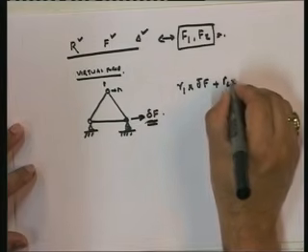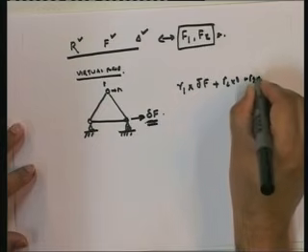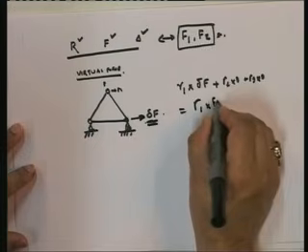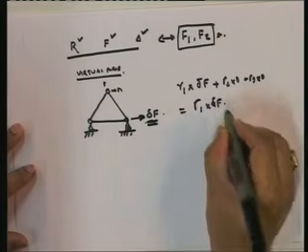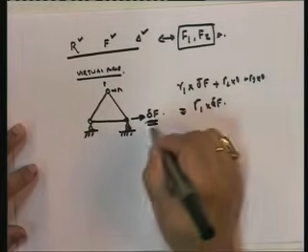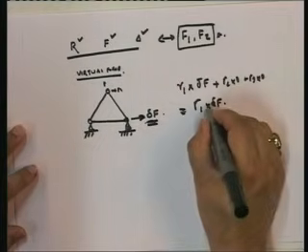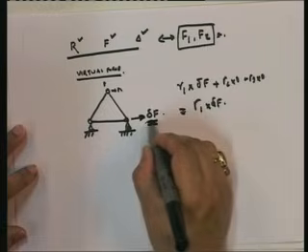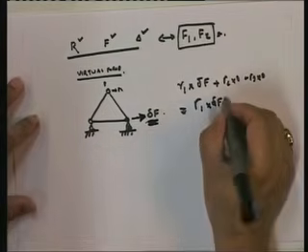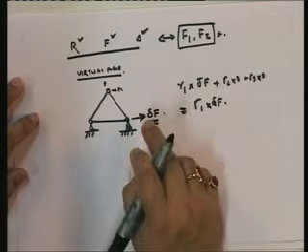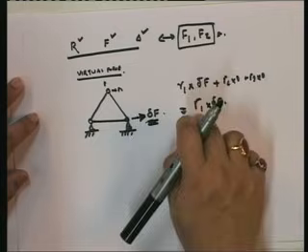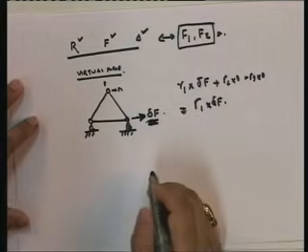So R2 times 0 plus R3 multiplied by 0 gives me essentially R1 times delta F. So my work done by the external displacements is actually just R1 delta F. That's the reason why I only apply a force here. That is the work done by this virtual force undergoing the real displacement.